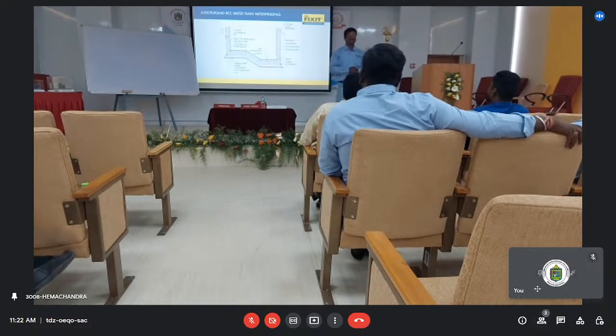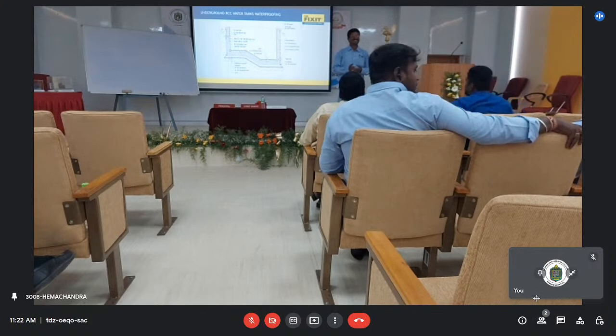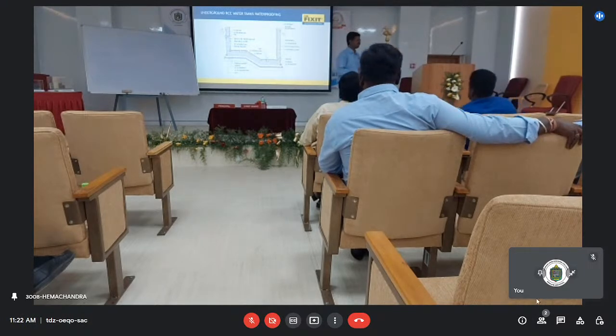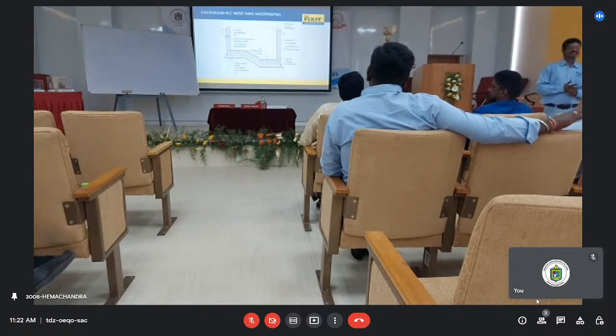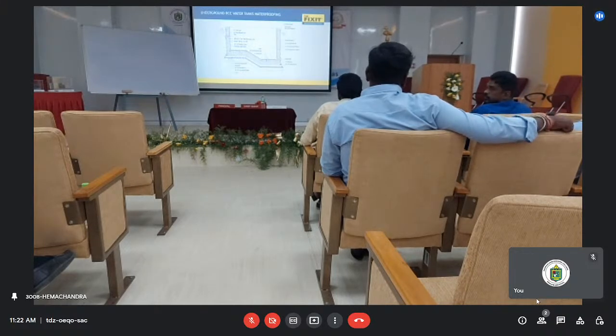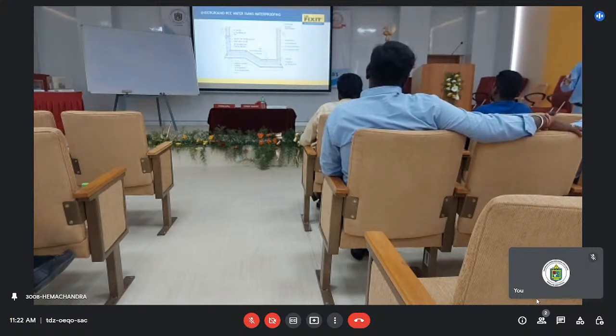Soil uprising, water table level. The water pressure coming from the water table level increases. To resist the water from the ground, we do the outer side too, because the water poured inside should not go out, and the water outside should not come in. So for any UG tank, underground tank, you have to do waterproofing on both sides. Inside also we do, outside also.